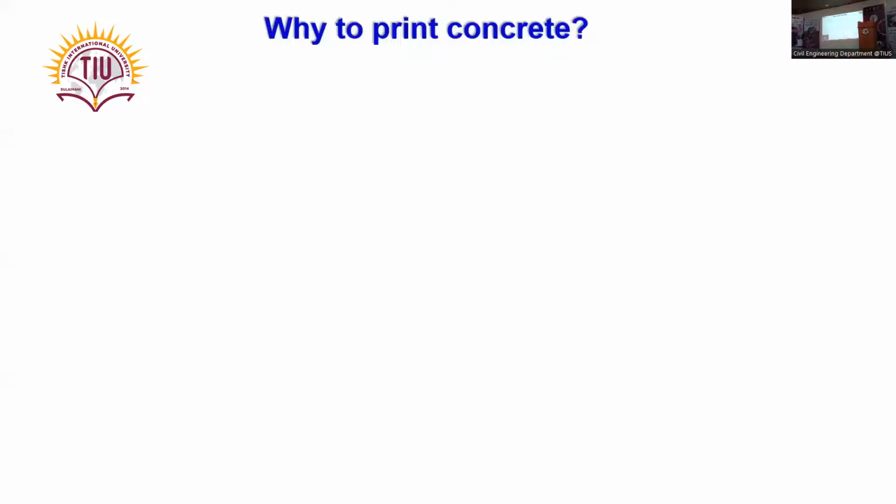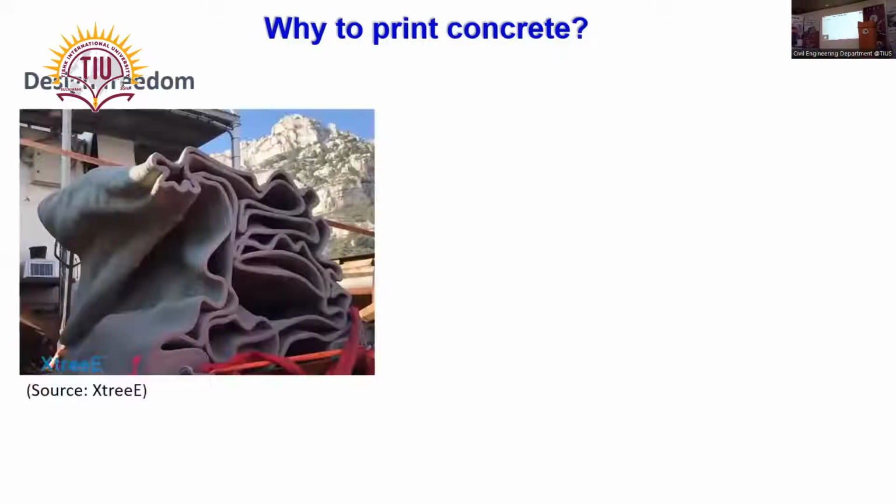For me, printing of concrete has a few reasons, but to be very specific, the first reason is design freedom. When we go for the traditional way of creating structures, we need molds and formwork, and when the structure is more complicated and complex, the amount of formwork and molds needed is again huge. It is also going to be costly and not affordable anymore when you want a unique design by an architect. In that regard, I will give more points to concrete 3D printing, because in front of you there is a very good example.